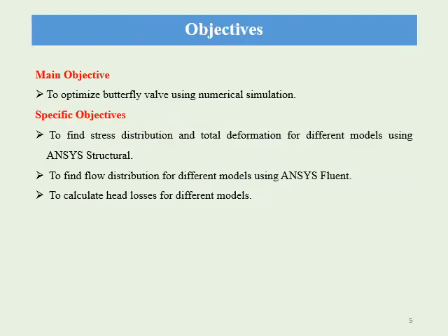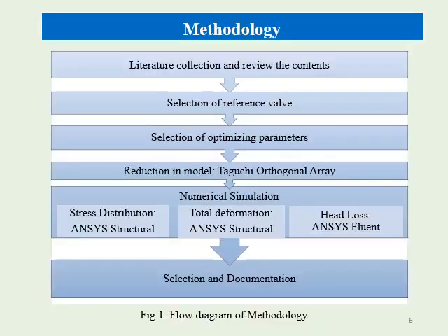The objective of our research was to optimize the butterfly valve design using numerical simulation. To do that, we needed to find the stress distribution and the deformation for different models, and we used ANSYS Structural for that. We needed to find the flow distribution for different models, for which we used ANSYS Fluent. Finally, we calculated head losses in order to compare the different models.